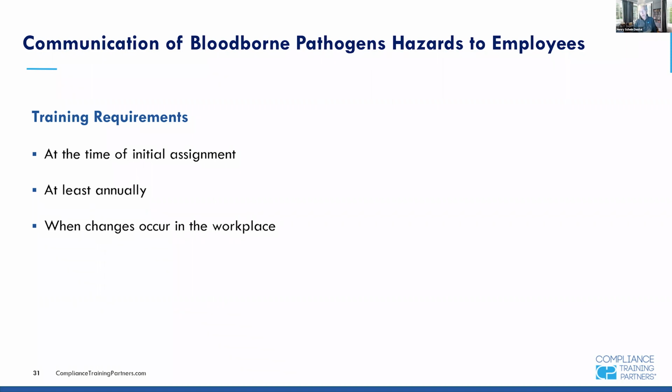It has to deliver basically half a gallon of water a minute for at least 15 minutes, and it has to be tepid, which means between 60 and 100 degrees. So it's got to be specifically designed for an eyewash. I've seen a number of people over the years get cited, get fined for having something that kind of, I'll call it a homemade eyewash from a hose or a particular kind of sink, and that just won't work.